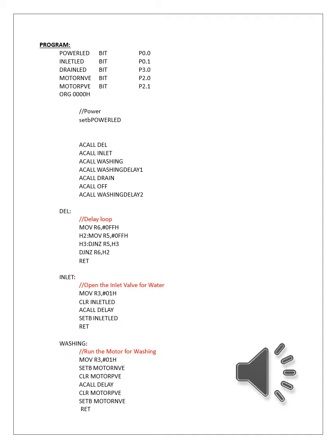So here, a call delay. Delay means it will go to the delay program. In the delay program, first we create a small delay. When the power LED is on, it takes some 1 second to turn on the inlet valve. So that delay we are creating.